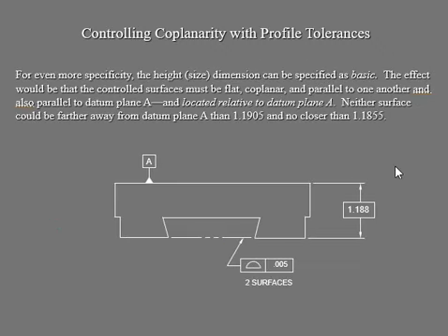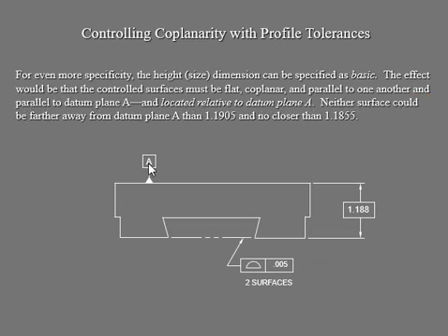And we repeat that with many different examples and different tolerances. Okay, your datum plane A. We'll look at the surface. Here is a control frame for the two surfaces. So we have coplanarity. And here the size is still 1.18 because in the same part, we are in the same example. So when you think about it, now that surface is going to be far away from your datum plane A, then 1.1905, or you can minus it out, so 1.1855. So you add it or you subtract it.